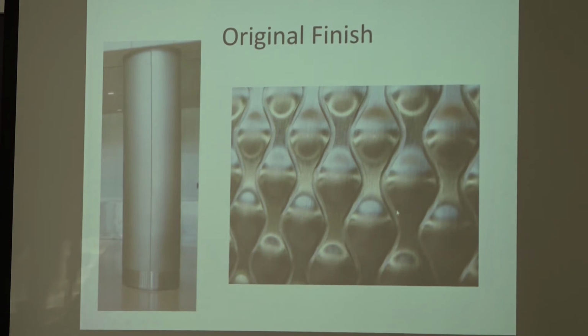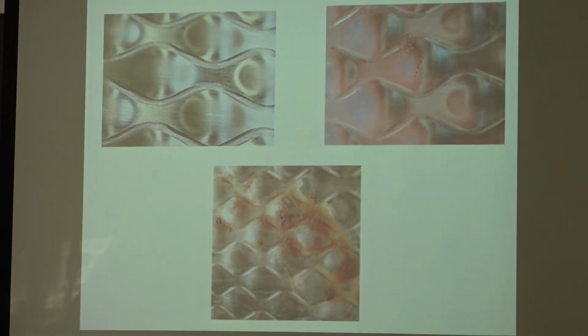And they have a good way of doing this. You can't brush with a steel brush. In this case, it has to be a stainless or a nickel brush because you're going to contaminate your surface if you use a steel brush. They had problems.